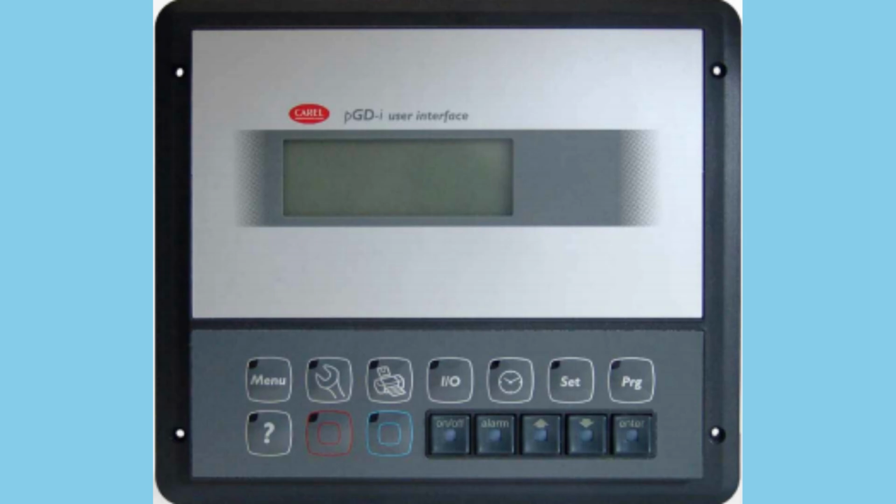System-level coordination. BMS sequences chillers, pumps, and towers to minimize total plant kilowatt-ton. It also provides chilled water and condenser water reset strategies, dynamically adjusting set points based on load or outdoor temperature.